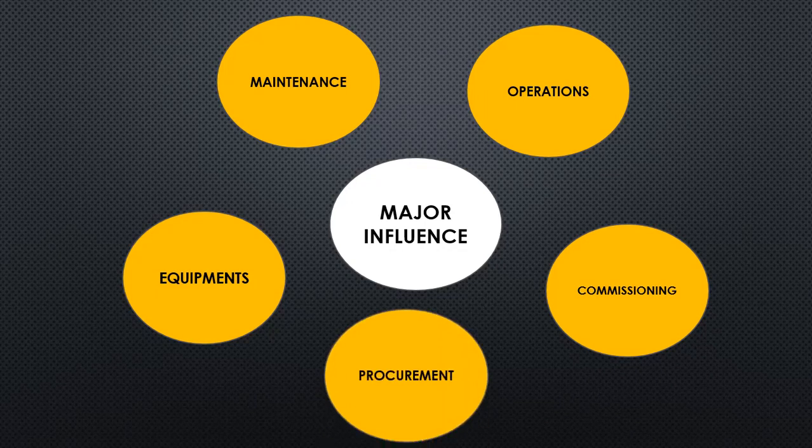The last one is procurement. Procurement is a process of buying or arranging the material. But this process has lots of activities to do. Activities such as writing a material specification, sending the request to the vendor and receiving the quotation from the vendor, evaluating the quotation, approving the vendor drawings and sending them back to the vendor, and receiving the materials and checking whether the material meets the specification or not. These are the different stages involved in procurement. So a piping design engineer should be aware of the sequence of the process to check the material status.